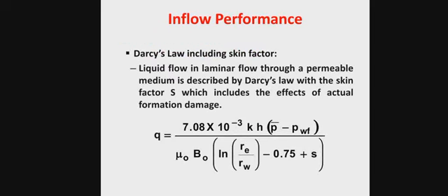In the inflow performance, you will learn about Darcy's law, including the skin factor. In Darcy's law, the liquid flow in laminar flow through a permeable medium is described with the skin factor S, which includes the effect of the actual formation damage. So S here is the formation damage. This is the Darcy equation, where Q is the flow rate, in barrels per day or cubic meters per second.